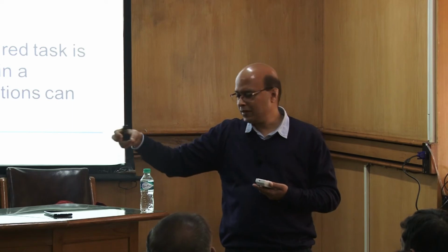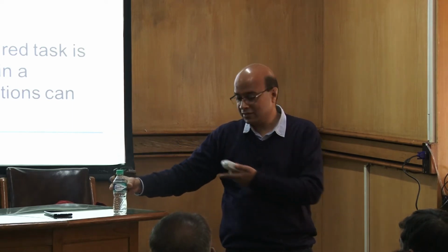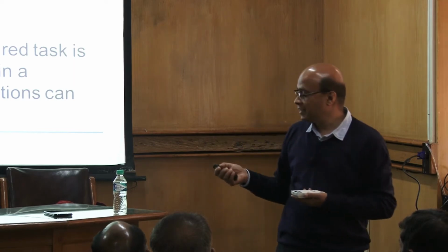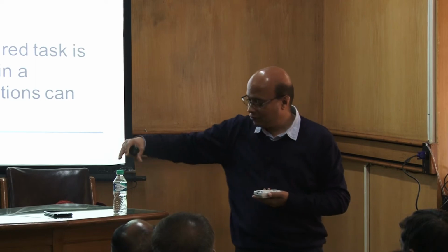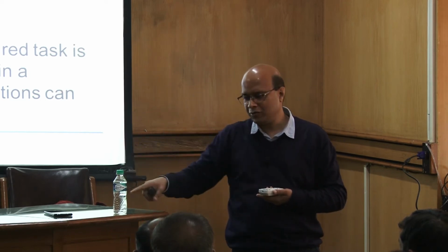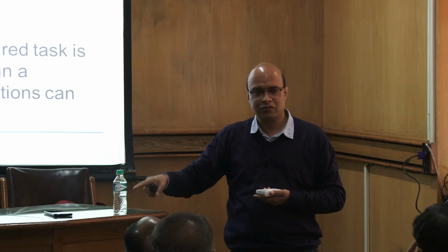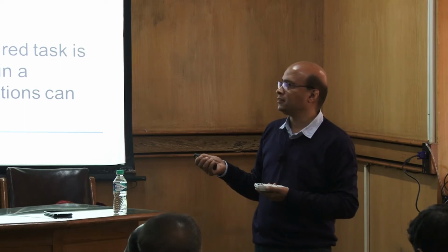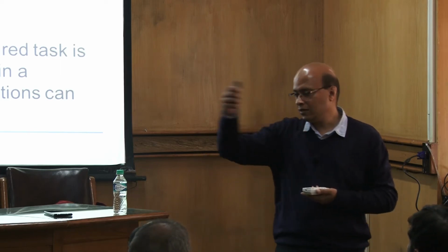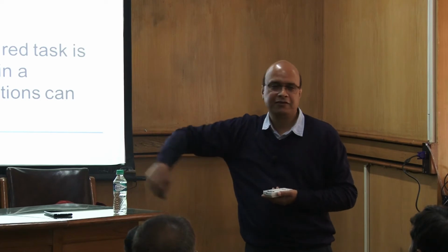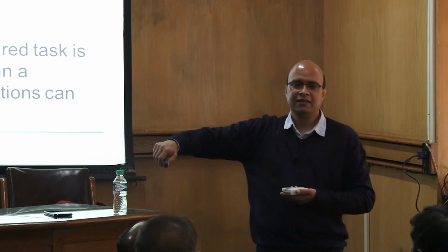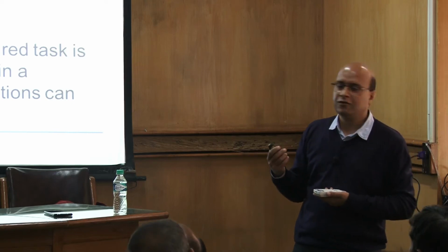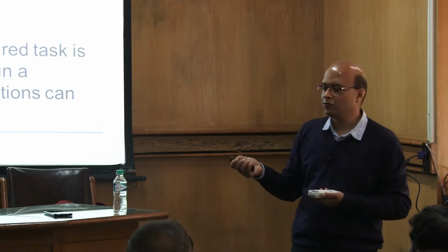So if I want to pick up an object, it's very easy to say, go here, pick up the object. But what is the position and orientation? It's very difficult to find out. That is why you can find these positions by using this one. You can manually take it there, and then in the memory it shows you the position and orientation. Now you know what it is, and then you can program it. The other thing is, this is very inefficient. Is it optimal whether I take the path like this or like this? There are infinite solutions. Which path will I take? So this is one way of finding out position orientations, but it is a very inefficient way of doing it. The efficient way is this one, once you know the position orientation.